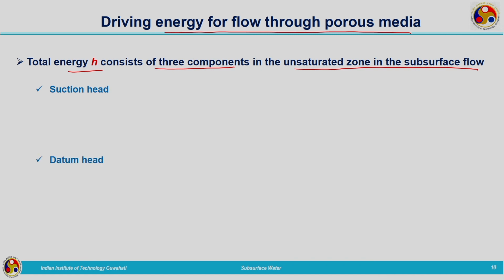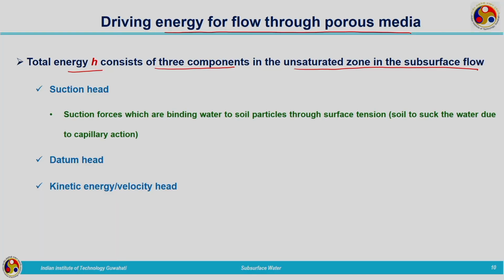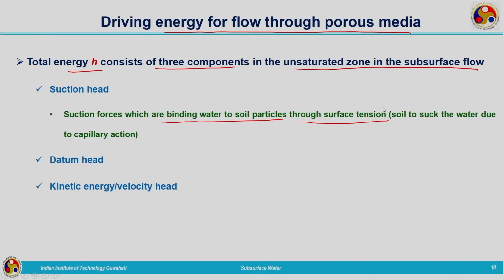In a similar way, we can write that the total energy consists of three components. One is the suction head, the second is the datum head, and the third is the kinetic energy head or the velocity head. In Bernoulli's equation, we were talking about pressure head, datum head, velocity head. The same thing here, instead of pressure head, we are using the terminology of suction head. What is suction head? Suction forces are binding water to soil particles through surface tension. That is due to capillary action, the water will form a bridge between the solid particles, that is also known as suction forces. And datum head is also termed the gravity head, and kinetic energy is the velocity